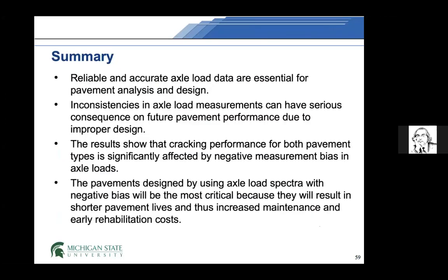Now, in summary, I will say reliable and accurate axle load data are essential for pavement design and analysis. So we are designing pavement for these loads. Now, most of you are designing using AASHTO. So you are going to estimate the design ESALs for, let's say, 10 or 20 years. So if your estimation of ESALs is not correct, that means you are over or under designing your pavement.